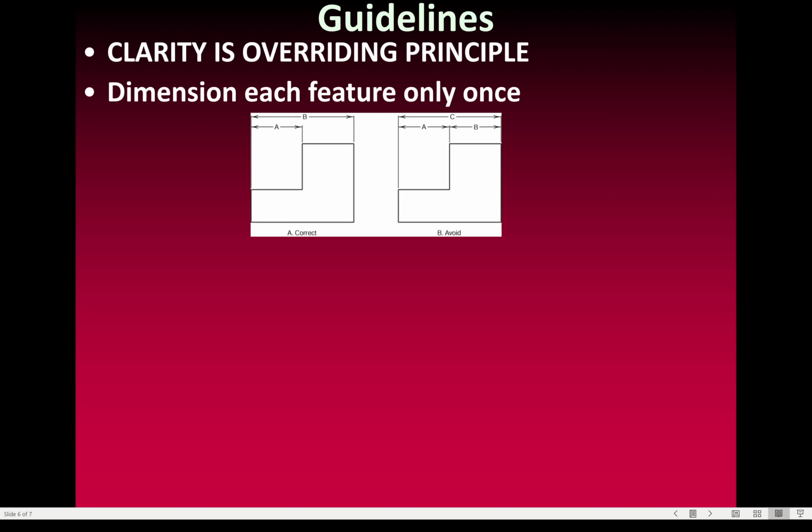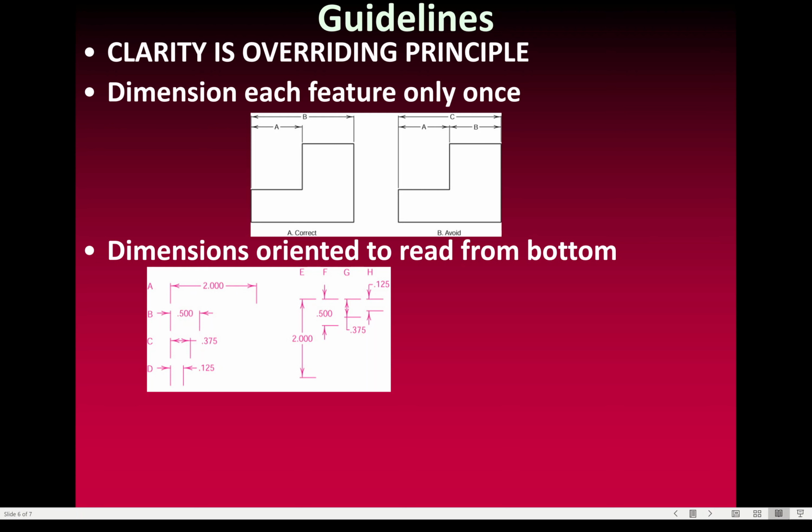And again, that's not super important right now for this class, but what really is important is that you do not put all of those. Only each feature one time. Even implied dimensions should not be included. Okay, everything should be oriented to go from the bottom.